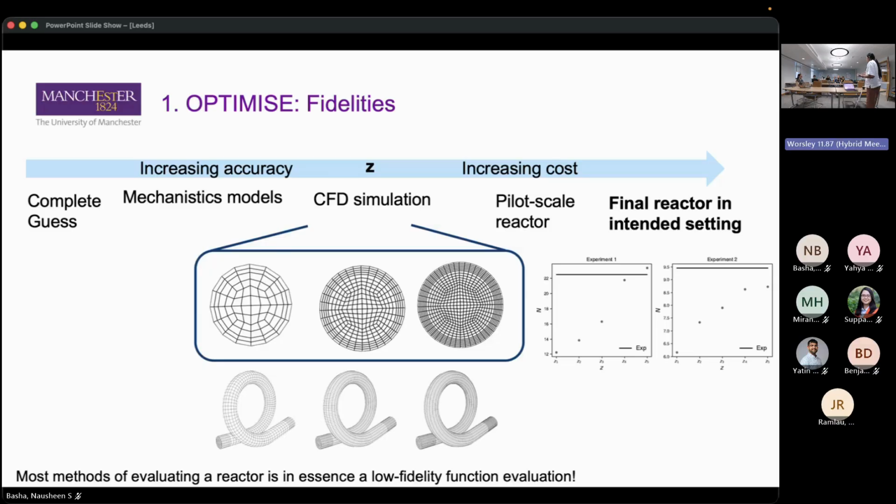So it's really hard to say how the exact match would be. Also, another phenomenon with CFD is that sometimes you could see a saturation. If you keep on increasing the mesh, at some point you reach a saturation or mesh independence, so you can see a flat curve. So you have to operate somewhere here rather than with this bit where it is already saturated.